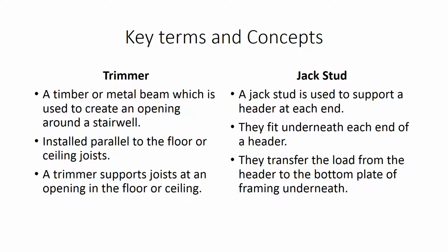A jack stud is used to support a header at each end. They fit underneath each end of a header. They transfer the load from the header to the bottom plate of the framing underneath.